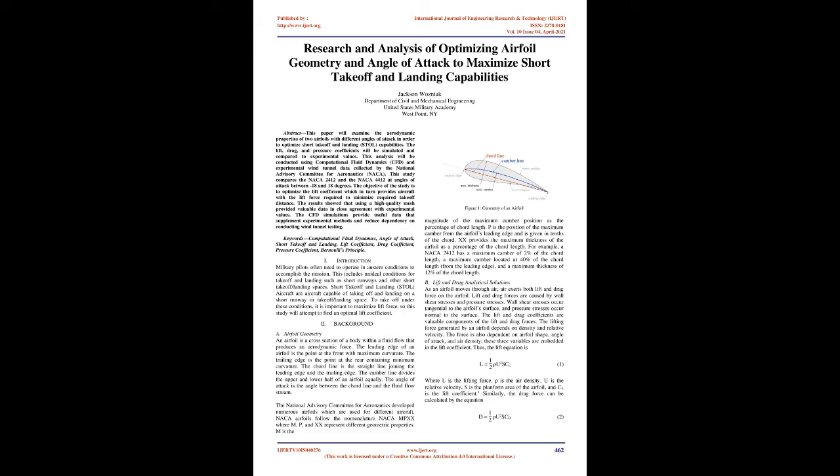The results showed that using a high-quality mesh provided valuable data in close agreement with experimental values. The CFD simulations provide useful data that supplement experimental methods and reduce dependency on conducting wind tunnel testing. Keywords: computational fluid dynamics, angle of attack, short takeoff and landing, lift coefficient, drag coefficient, pressure coefficient, Bernoulli's principle.